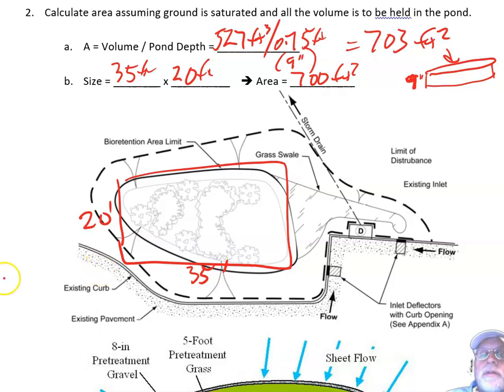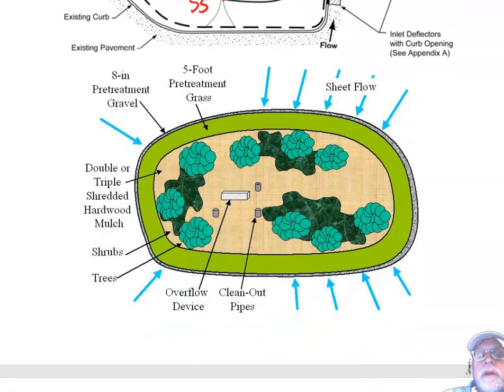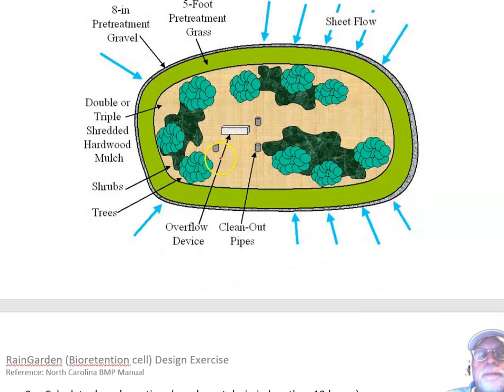So that's what we're going to do for the pond size. And again, we're running the water off from a parking lot there. How it gets there, I've seen a number of these. Some of them actually have a little culvert running from the parking lot to the rain garden. It's better if we can run it over the land, sheet flow, and we have some grass around it, so it runs over that overland in there.